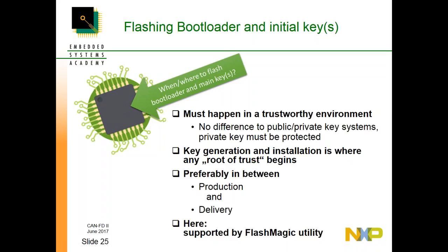If you look at the term root of trust, you see this also with other chip manufacturers. I've actually seen somewhere recently that now you can get services where the private keys get installed directly at the chip manufacturer during the production process. And they claim, well, then you don't have to worry about it, you trust us. Well, my biggest problem with something like that is it means that at this location where all these millions of chips are produced, there is somewhere a very large database with all the keys installed, and that must be a nice lucrative target for some of the hackers and hacker groups out there.